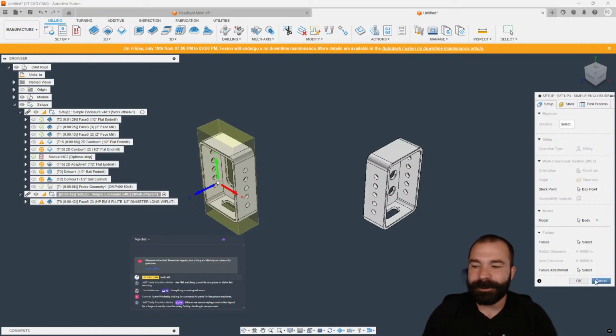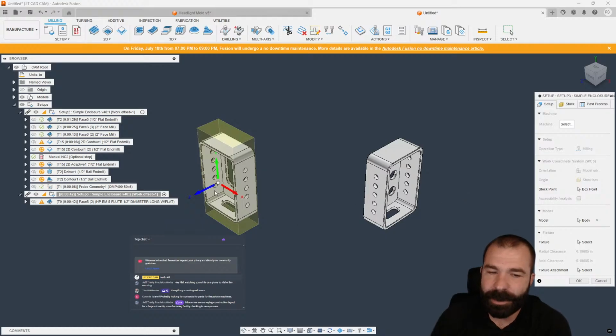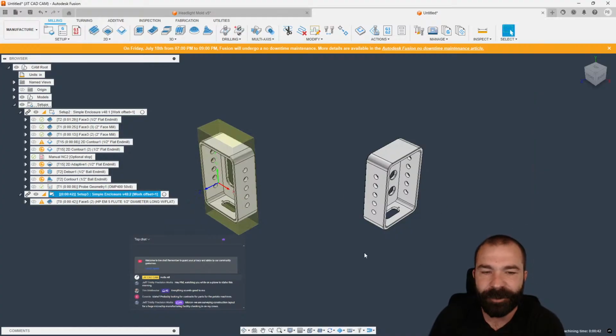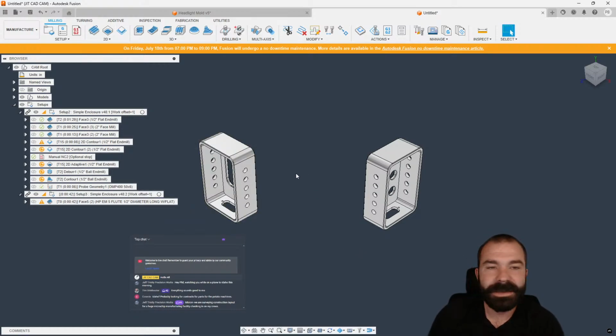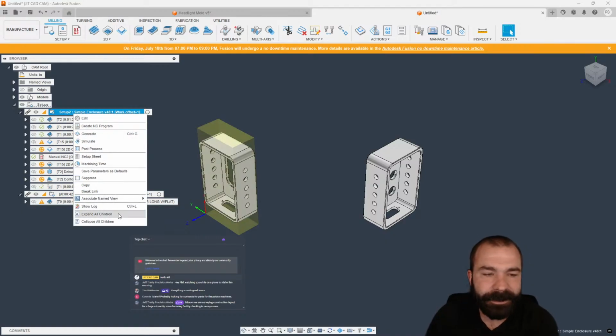Again, as you guys are seeing, this is where I really need to get some content out there for you. We've had this problem in the past when you start to run parts on a tombstone. I know Autodesk is looking into it, but as you can see, when I try to bring in 2 of the same part on a tombstone, right? Maybe I want to run 2 of the same parts in setup 1, setup 2, and then different parts, we keep having the problem because of the model. When you go into the fixtures as well as the model for manufacturing, it keeps trying to tie itself back to the same thing. So, as you guys can see, again, a couple of different ways, and as all of you saw me do already, collapse all children is a very easy way to fix that dilemma.